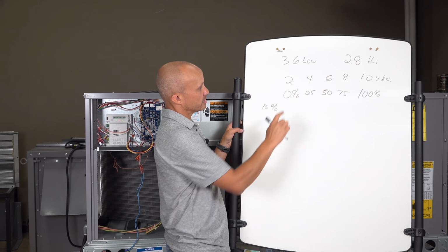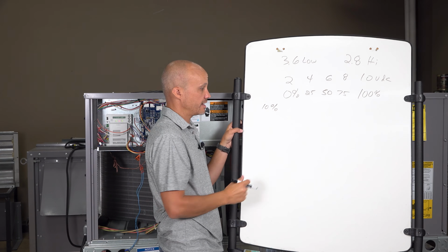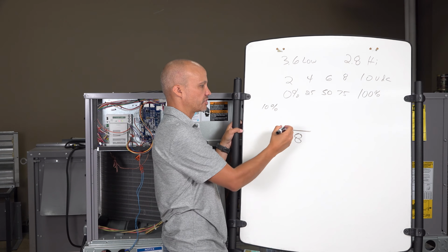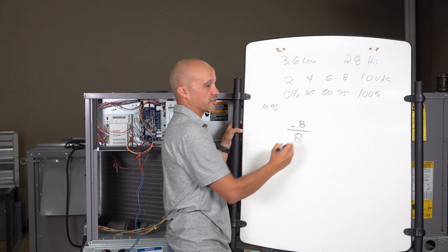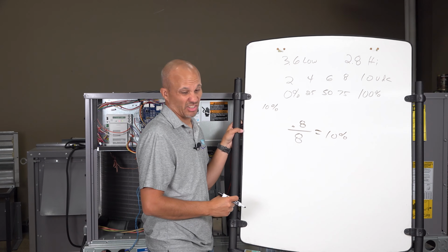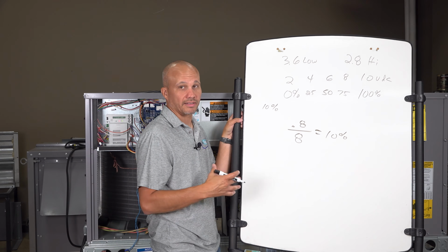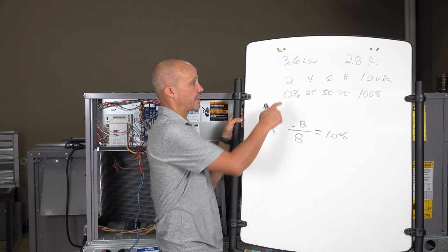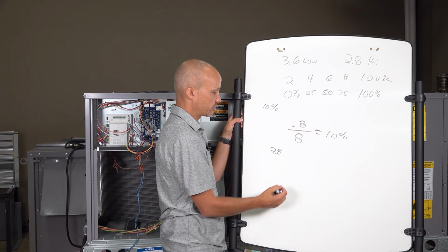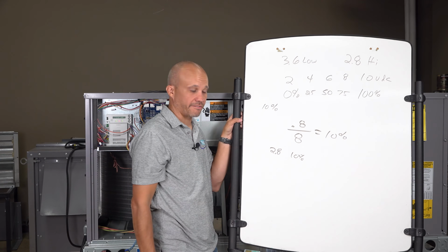The way it works is that from 2 to 10 volts, that's an 8 volt span, right? And I want to go 10%. 10% of 8 is 0.8. For those of you that love math. I know that gets a little bit weird and annoying, right? But I want to set that for 0.8. But it's not 0.8, it's 0.8 above the minimum. So 2.8 volts, that's 10%. So our default high fan speed was 10%.